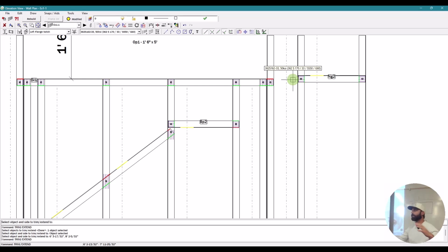So as we're going through the engineering process, if it looks like 15,000 pounds of that is going to be 6-inch and 18 gauge, then we might go slit those coils ahead of time and have them ready, and then leave the rest of the master coil for down the road, whether maybe the next project is 3 5/8 18 gauge. But that way we're not having 6-inch 18 gauge coils sit on our floor for 8 months because the next project we needed was a 3.5 18 gauge profile.